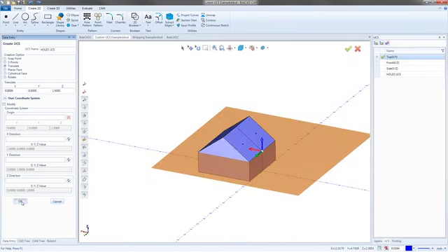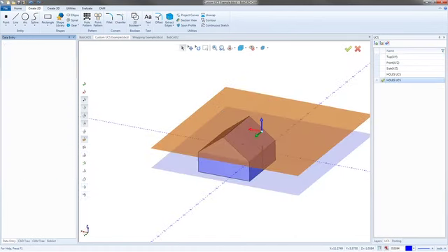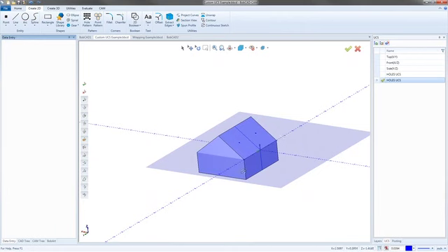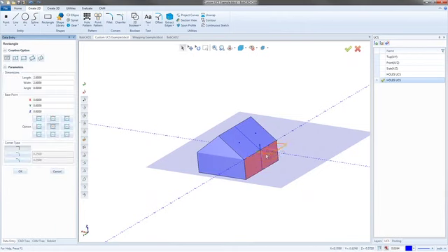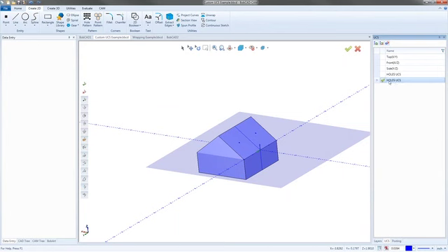So now if I hit OK, it's going to make that plane. Basically that location is now kind of the new 0. Anything that I draw is going to automatically go to there, but not down to the bottom of the stock where the old 0 was. So the UCS controls all of that stuff. This is the wrong name, but it'll work. There's our 2. That's fine.